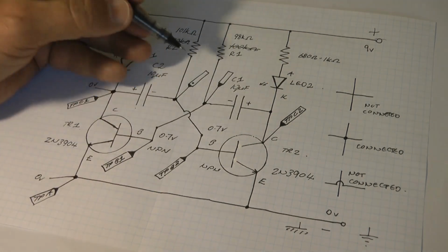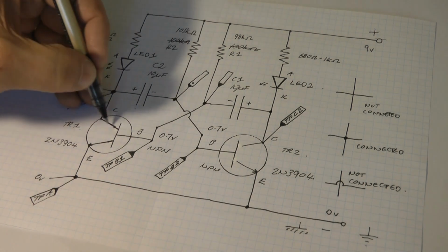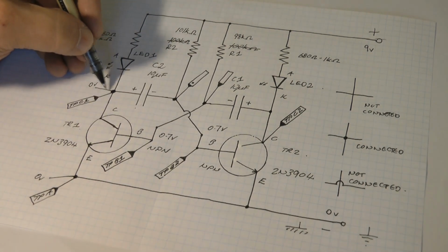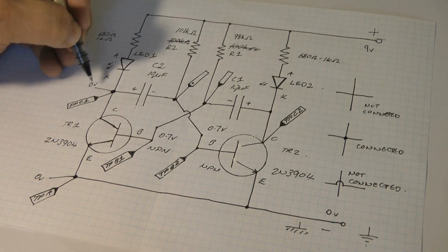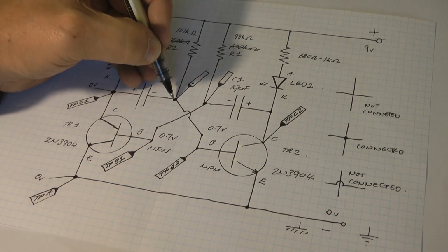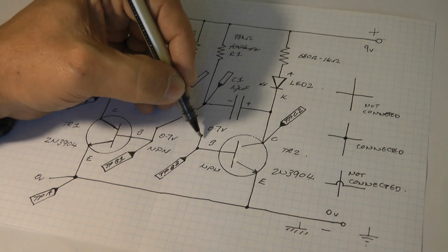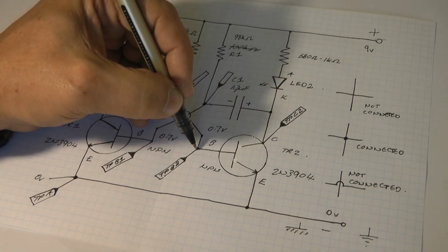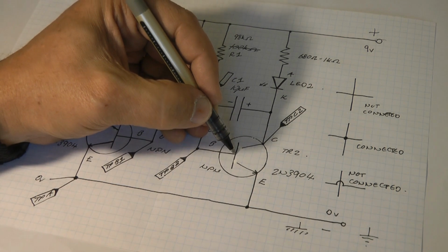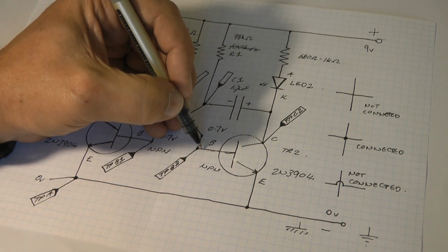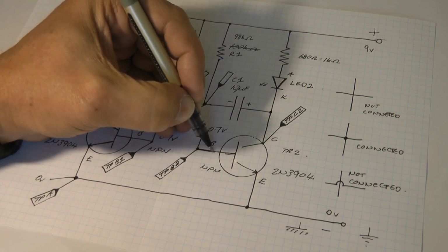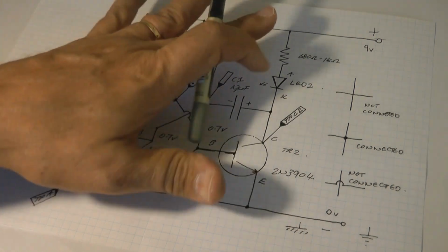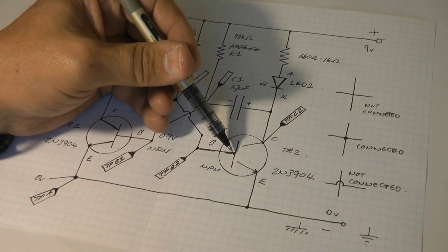And that's what's happening here, is as this transistor comes on and it forces this down to 0 volts, and the capacitor forces this point, which is connected to these points, down into deeply negative territory, that immediately switches off this transistor, which might have actually come on for just a brief instant as the whole circuit powered up.